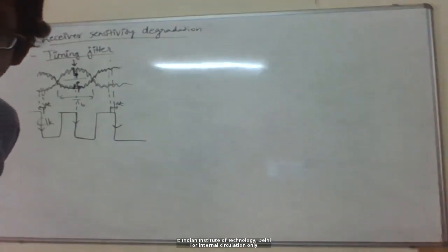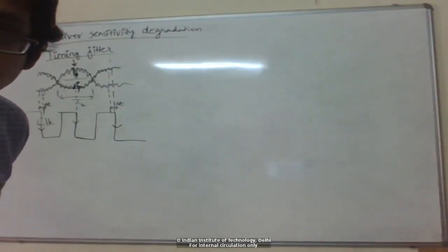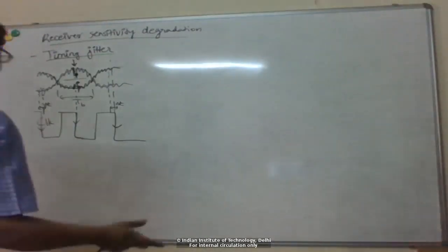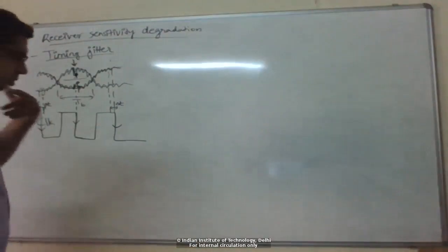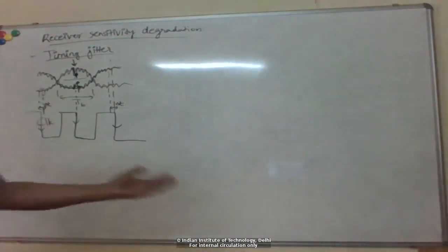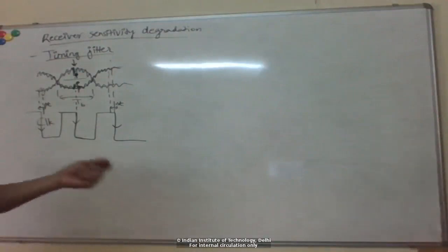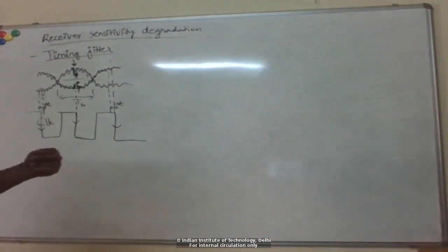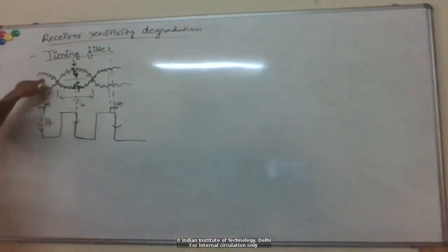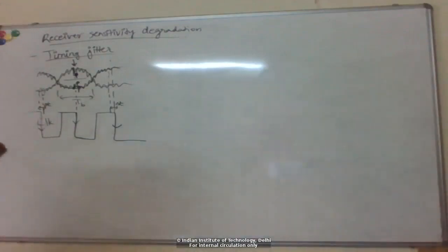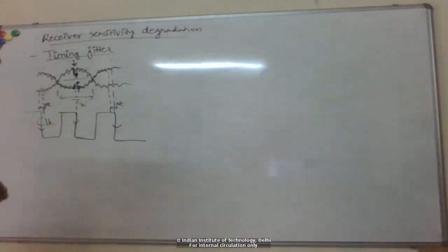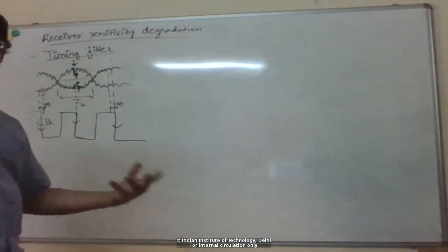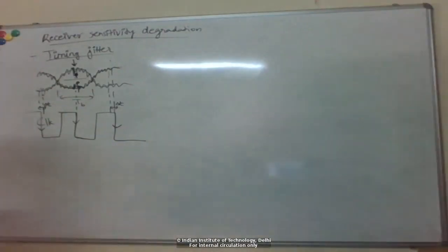So the question is, since the clock is periodic, the clock jitter will lead to a cumulative effect. The argument here is that the clock is not perfectly periodic. Of course, for any traditional clock source which you get from some oscillator, the oscillator has a well-defined frequency of oscillation, which gives an output at that particular frequency. But here, because we are recovering the clock from the received bit stream, there is no natural frequency. There is no oscillator which is defining a natural frequency of operation.